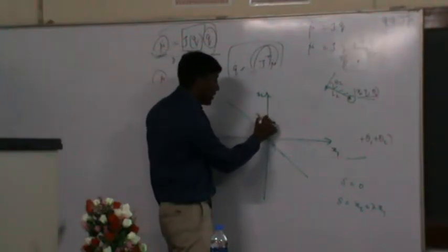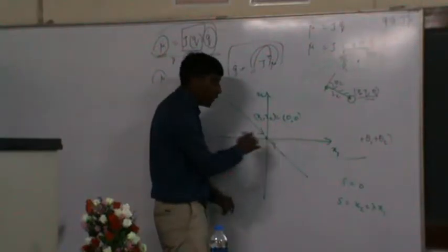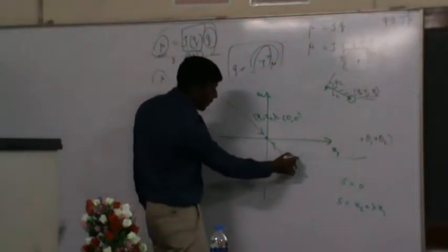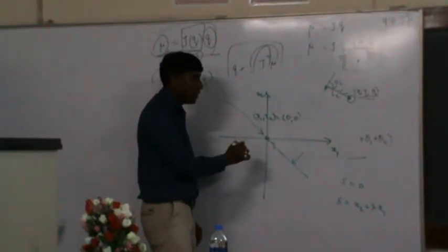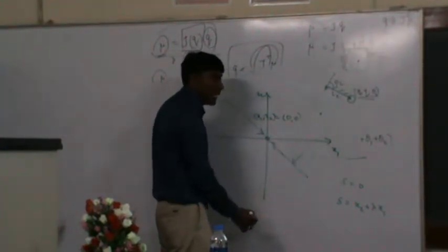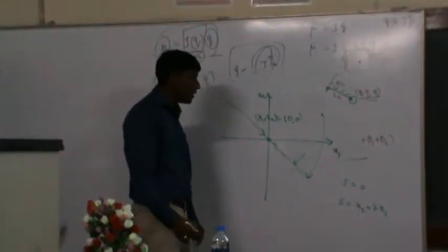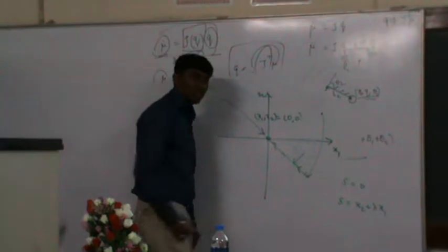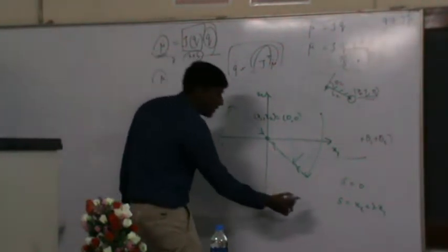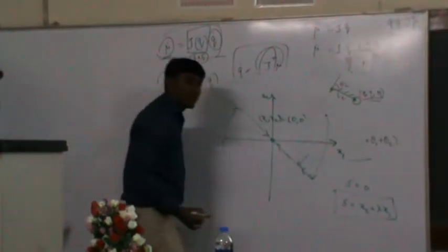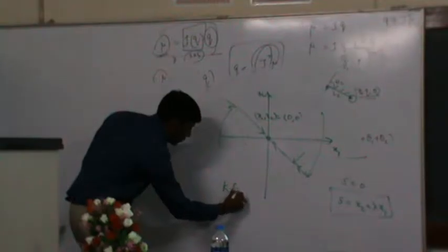Here I will take the equilibrium as 0, 0, so that is the way I draw. Whatever comes and hits will try to reach the stable point. You just start anywhere here. You need to make a switching region, then you have to have a sliding region. Correct? Now, if you use a classical sliding mode, what is the problem? You have something like the controller k into sign of s.